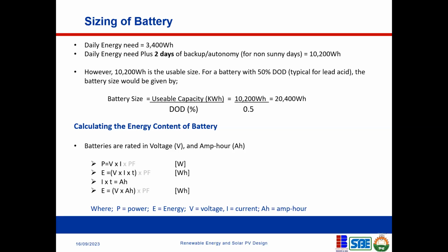When you want to take watt to kVA, to VA, you divide it by 0.8. And when you want to convert it back to watt, then you multiply by 0.8. That's for the load. But like it was said before, when you are dealing with DC, then you don't need to consider the power factor. Most times, the wattage is also the kVA rating.